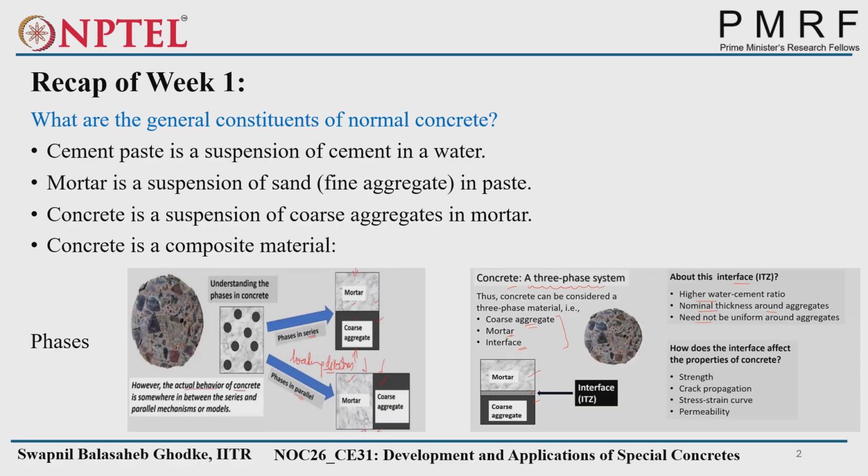Not actually. The thing is that it will not. As you said, we are already using superplasticizer. Cement content is less than normal concrete. But whatever extra cement is available which does not get hydrated, that unhydrated cement will act as a filler. That quantity will be less, but it will act as a filler. Yeah, but we are already reducing it with the superplasticizer. It will not be that high.